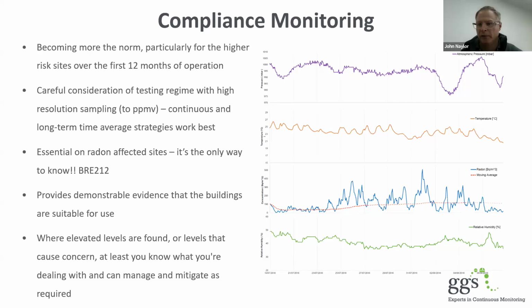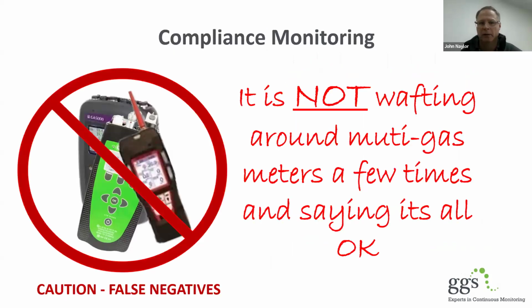So again, that's compliance monitoring, very similar to the investigative monitoring. And there's, again, more things you can do. In fact, very similar methodologies and tools you can use to show that it is effective. And I'm going to raise this message again: it's not wafting around an analyzer a couple of times and saying it's all good. We're going to get false negatives, a false sense of security that it's all good. And it's not based on science. It's not based on what the changes are in the gas regime going on. So if you're seeing that, or you're doing that, please really think about what you're doing.